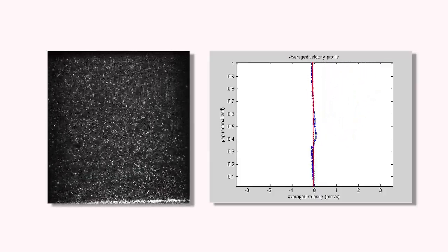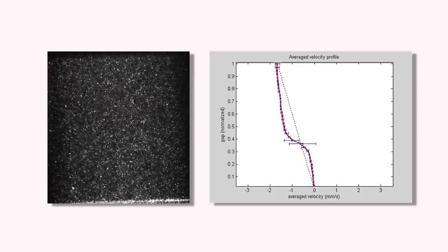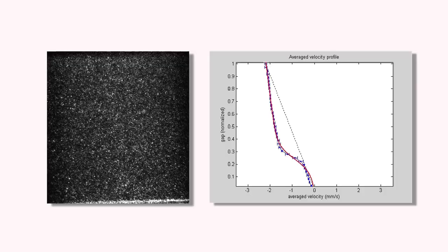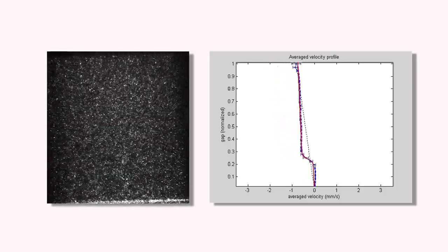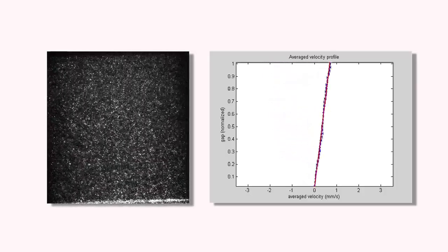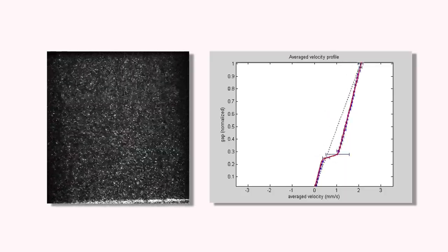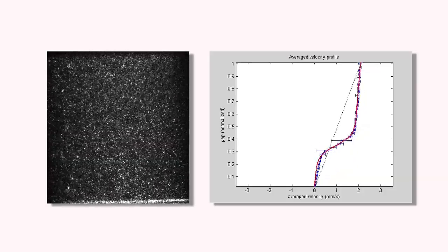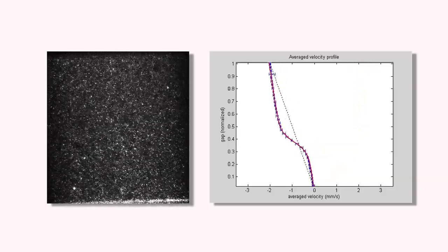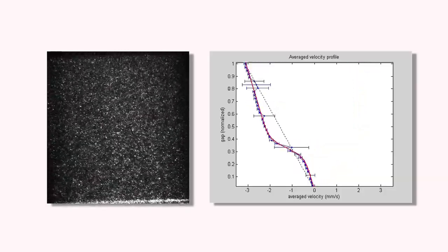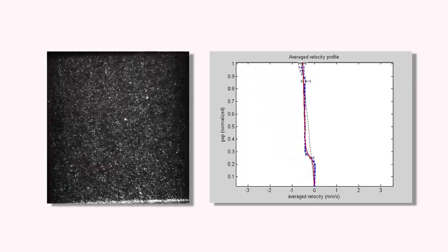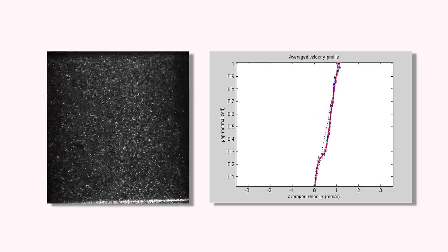The position of the band and the extent of the band depend on both the time and the strain amplitude. It's linear, and it becomes progressively nonlinear at large shear rates, and then when the flow reverses, it comes back and is linear, and then becomes nonlinear again. So if you can't see inside a complicated material, that could indeed be affecting the nonlinear rheology that you're measuring.